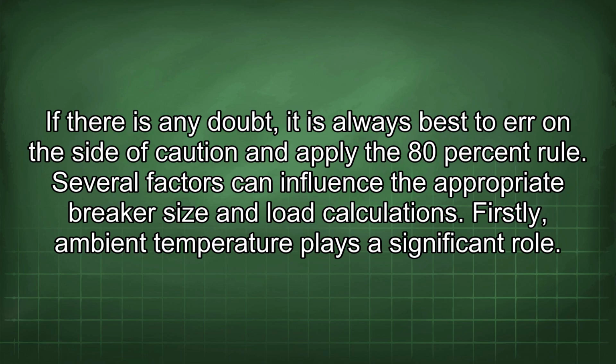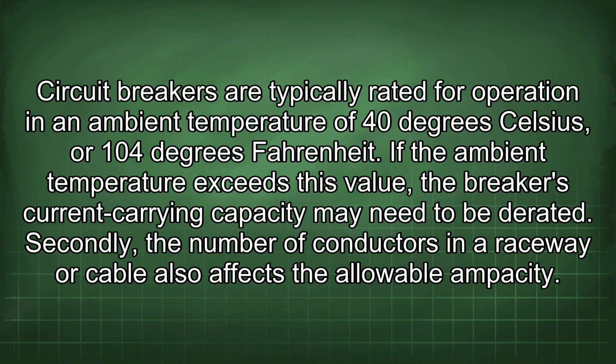Firstly, ambient temperature plays a significant role. Circuit breakers are typically rated for operation in an ambient temperature of 40 degrees Celsius, or 104 degrees Fahrenheit. If the ambient temperature exceeds this value, the breaker's current carrying capacity may need to be derated.